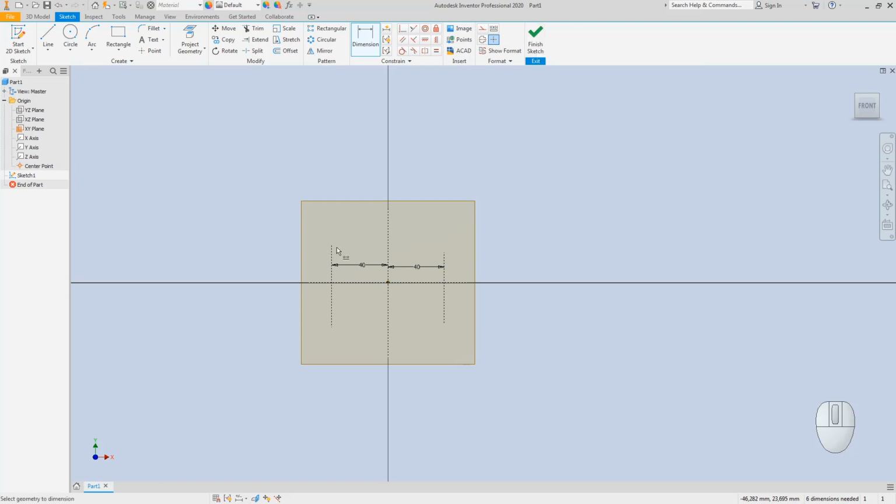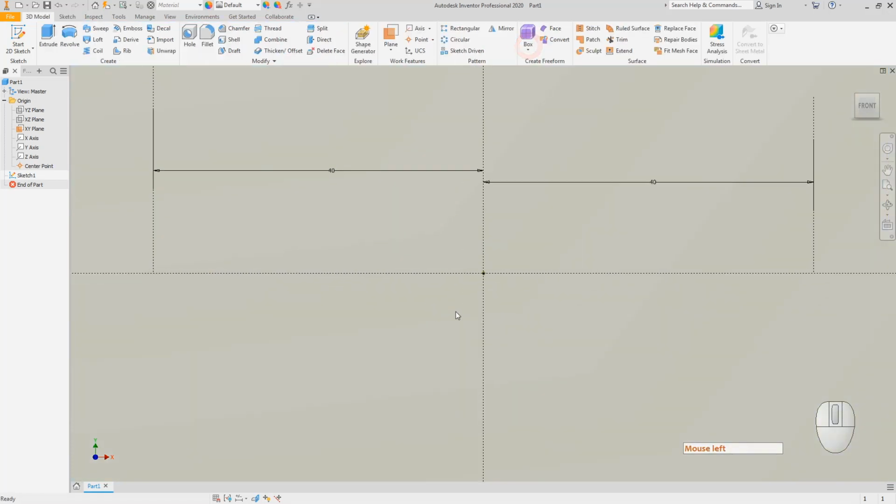After these tools, I'm going to just create two sketches at these points. For this, I will use the points of these intersection lines. For that reason, I will just create those points in order to create the planes at these points, which is these 2 points. I will use those points.